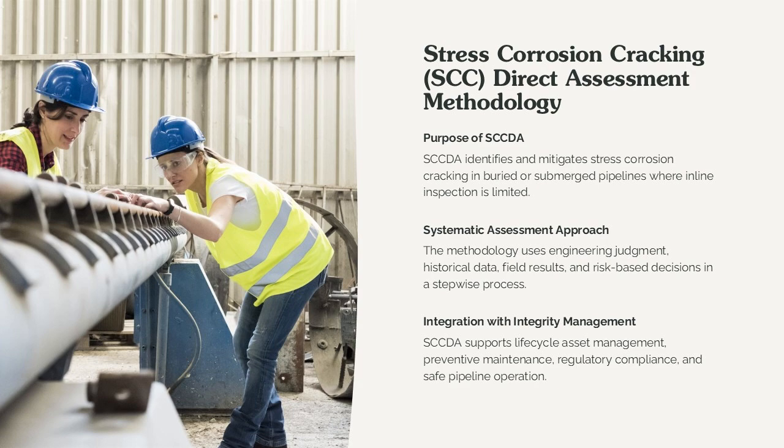SCCDA is a structured, integrity management process developed to identify, evaluate, and mitigate the threat of stress corrosion cracking in buried or submerged pipelines. The methodology is primarily intended for pipelines that are not currently inspected using inline inspection tools or where ILI data requires supplementation. SCCDA emphasizes a systematic, step-by-step approach that integrates engineering judgment, historical data, field inspection results, and risk-based decision-making.